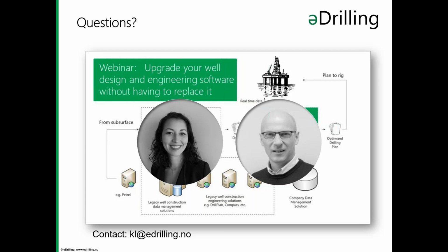The next question is how accurate is the modeling of cuttings generation, transport, and settling? We have an embedded solution for this in our model, where we model all the different phases in the fluid and also the cuttings, including the slip velocity of the fluid, so that we have a cuttings concentration in the well.